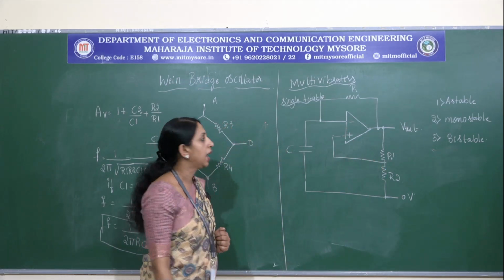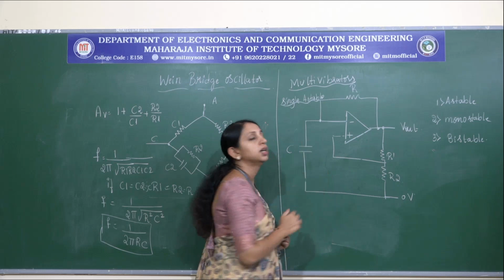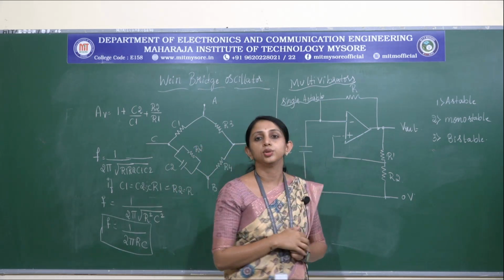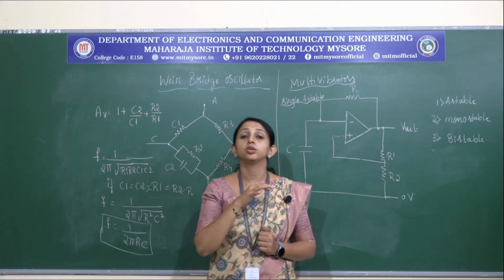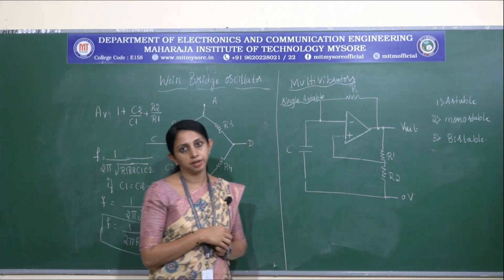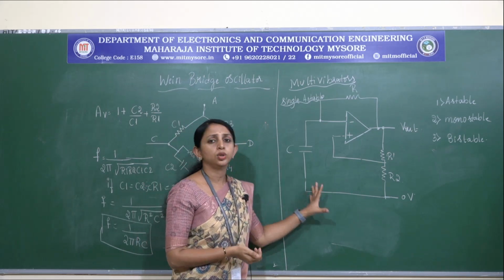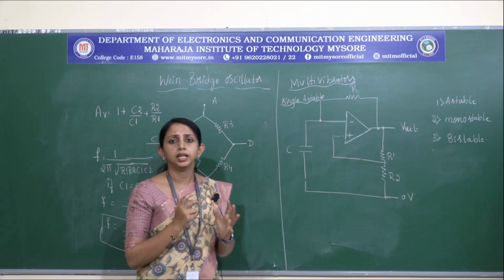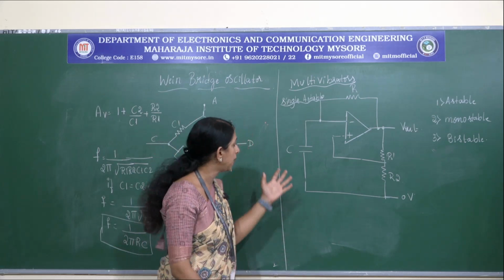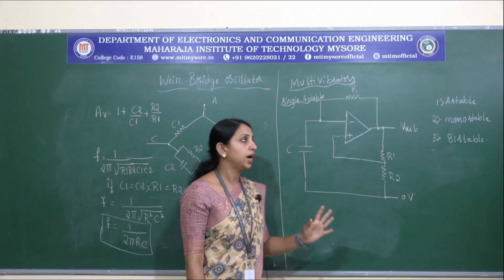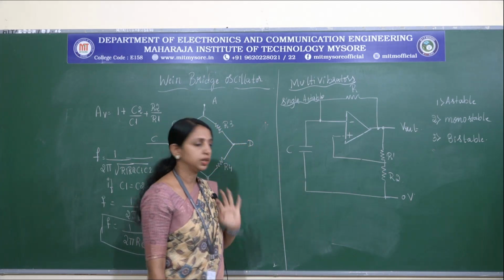So after that we have an R value here. Why is the R used? That resistance is used in order to adjust the frequency of the astable multivibrator. In order to analyze this particular circuit, let us assume that initially the capacitor is uncharged.